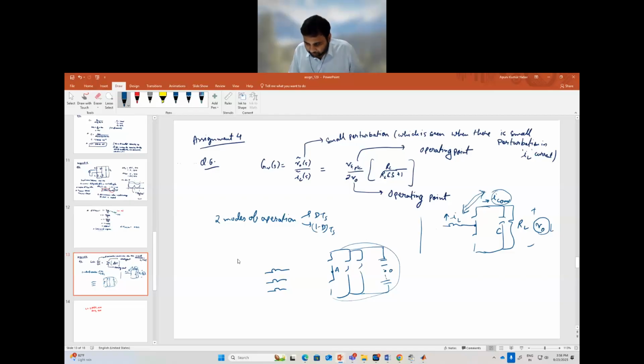Then this is connected over here with the N point, the neutral point. Between this neutral and the O point, you will see one DC component coming over here, which is called the VNO voltage, the common mode voltage.